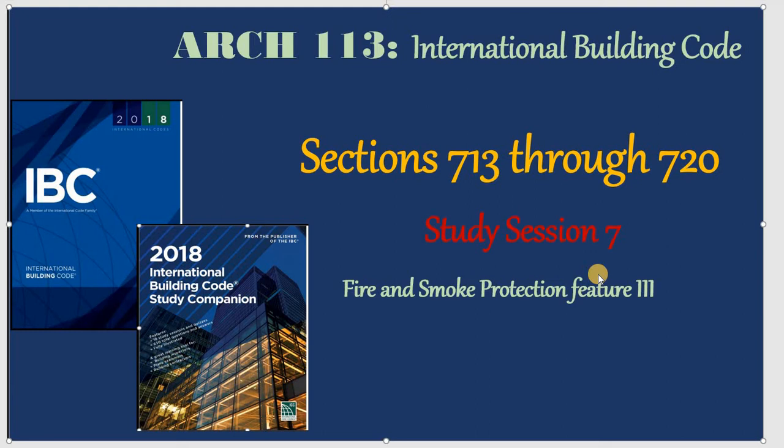We need to follow the code, the International Building Code, to make sure that all of the materials qualify for fire and smoke protection. Also, we need to design depending on the occupant load and the group of the structure. So that's why there are many requirements from the code for fire and smoke protection.